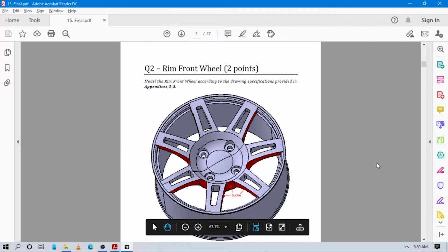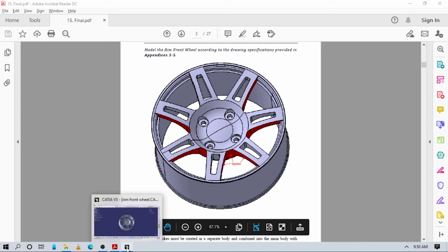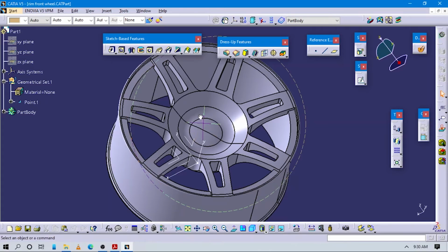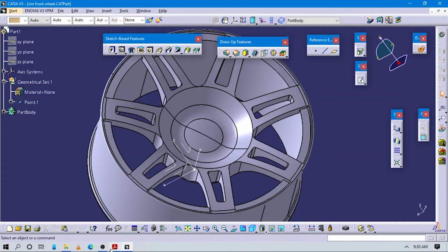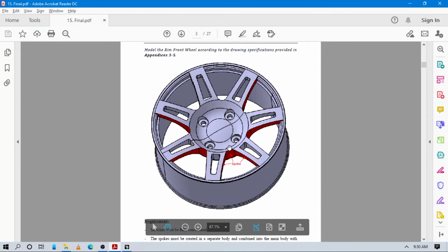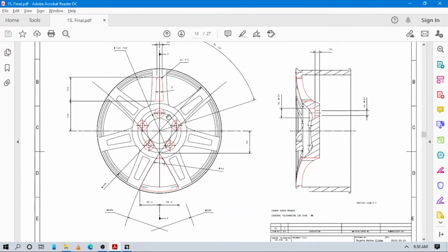So welcome guys, and let's start to complete this assembly. In the previous video we had completed this part up to here. So the last part, these features, we have to add to this wheel train. The features means these holes we have to create here. Here you can see these holes, 1, 2, 3, 4, 5 holes we have to create on this wheel train.